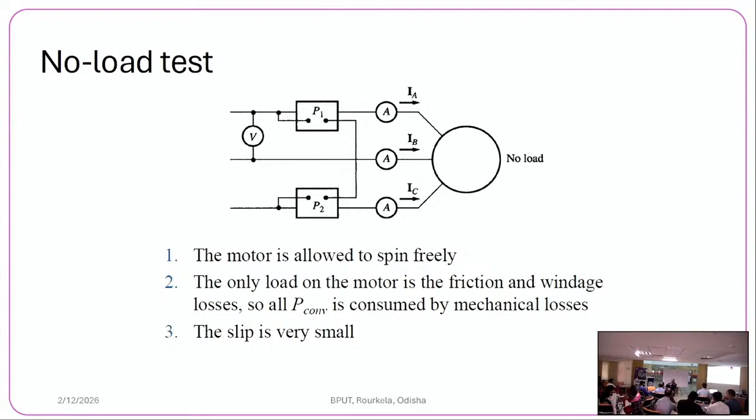It is not always 1.1 or 1.2. It depends upon the frequency. But considering 50 Hz frequency, it is around 1.1, 1.15 or 1.2, within that range. But if the frequency is say 10 kilohertz, resistance will be very large. The multiply factor is not 1.2. So that's why in the DC test we apply DC voltage and measure the resistance. For effective R1 we multiply by a factor of 1.1 to 1.2.